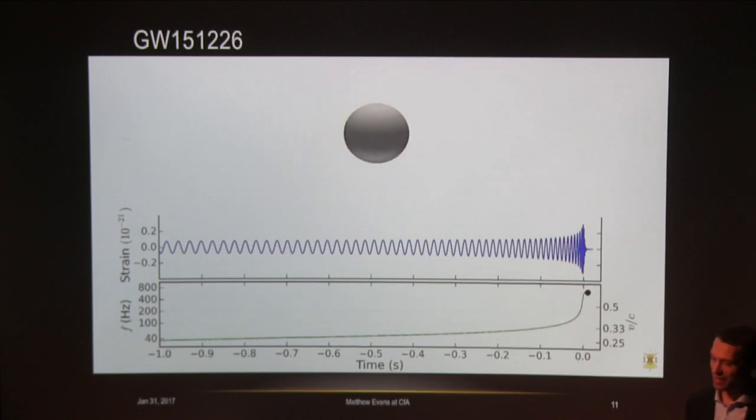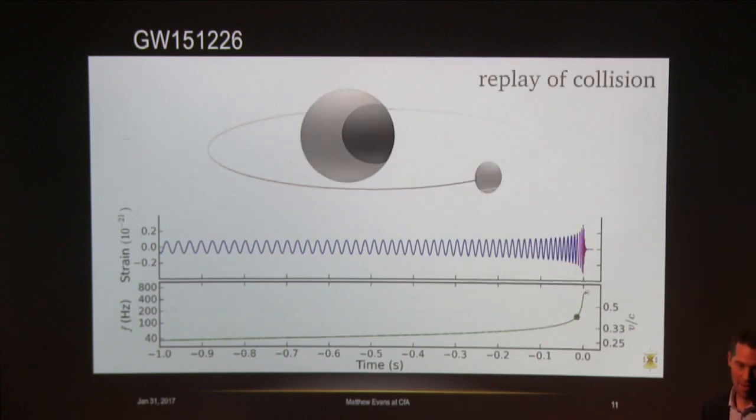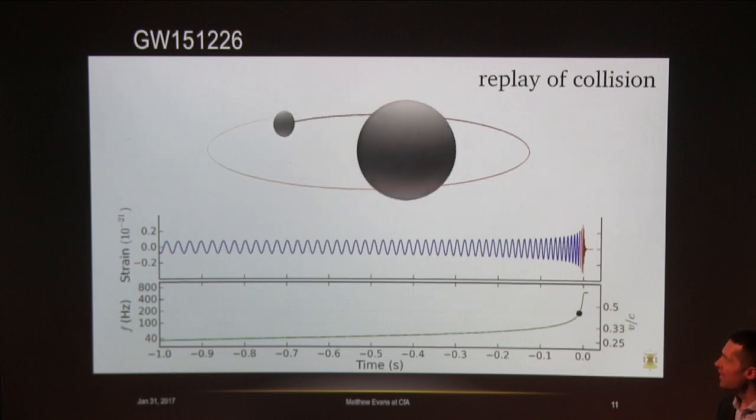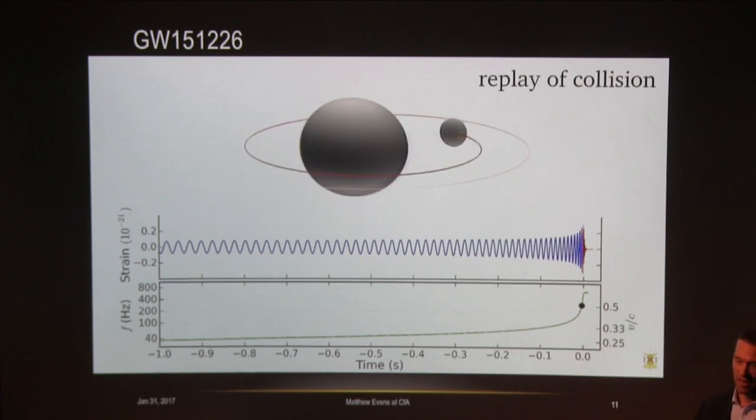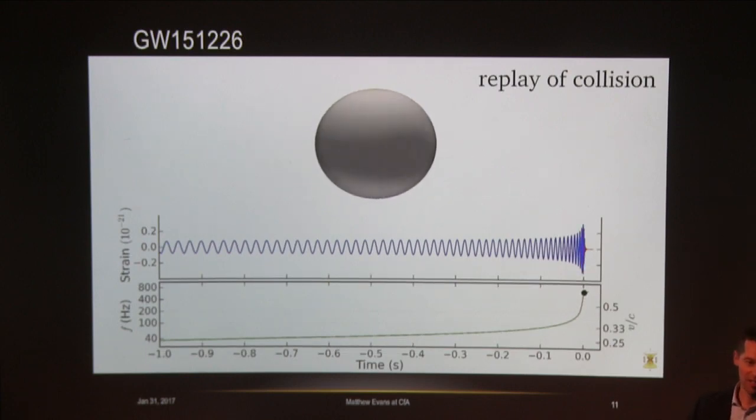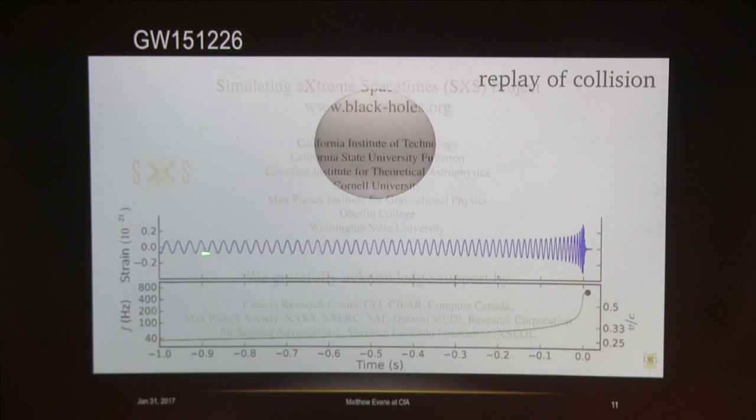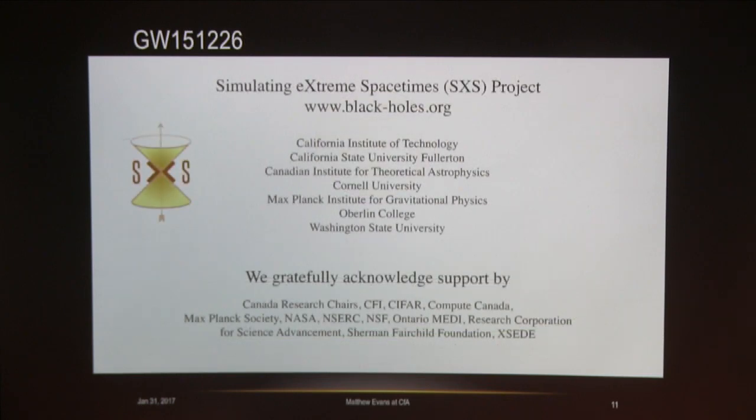For the first event, you could take the time series that came out of the detector, do a little bit of filtering on it, and put it on a time trace as if you're looking at an oscilloscope, and you could see the thing sticking out. For this, you need to do matched filtering in order to integrate the SNR of all of these cycles as you go along. Right? So it was a much longer sort of thing. You integrate up the cycles, you have a good model, and you get a good signal-to-noise ratio, but it doesn't look visually impressive.